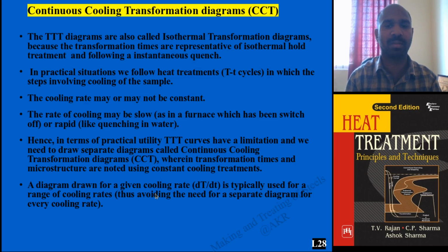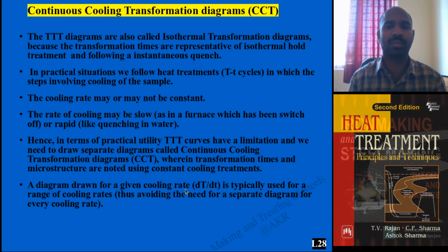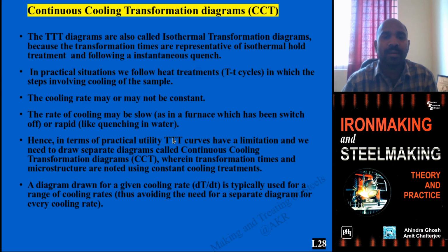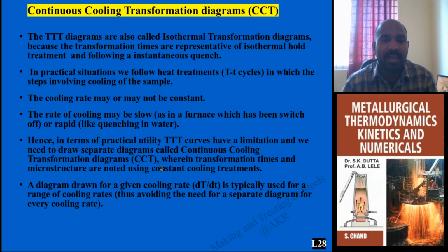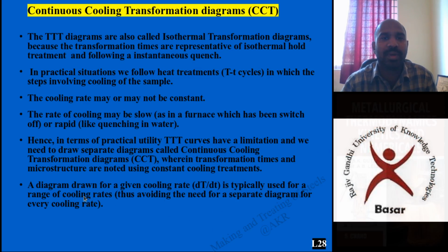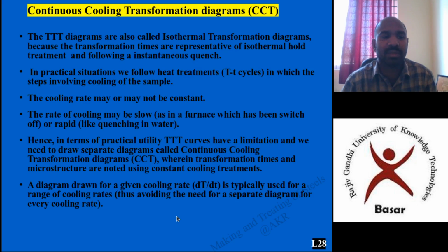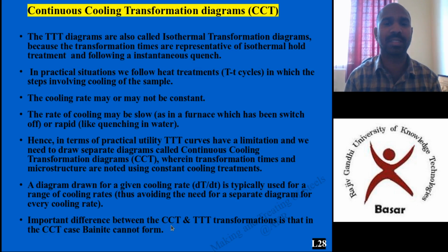This diagram mainly gives an idea about the cooling rate, the change in temperature by change in time. You need not draw a separate diagram for each and every cooling rate. If you take a differential of these things, you can draw for a variety of quenching media at different temperatures. You can draw one cooling curve. That is done in this CCT diagram.